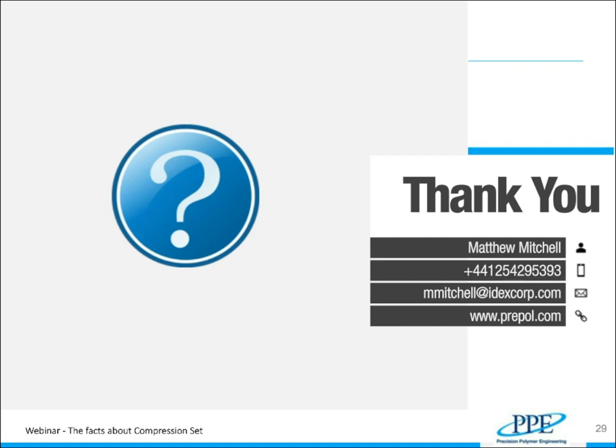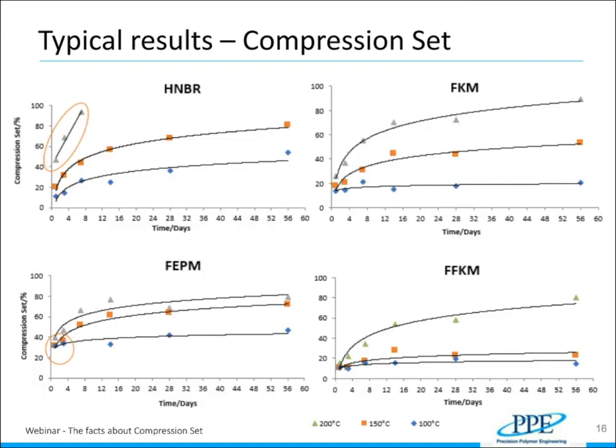Okay, thanks Matt. How does EPDM compression set or CSR compare to others such as FKM? Yes, so I tried to show that in the slide, if we can find it in the data. EPDM is kind of similar to, say, an HNBR. It has a very similar kind of behavior in that, within the temperature range over which it operates and has been shown to operate well, you'll get that very classical initial increase, and then it will plateau at some point.